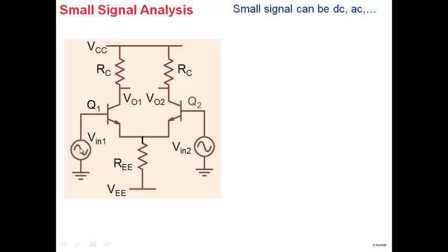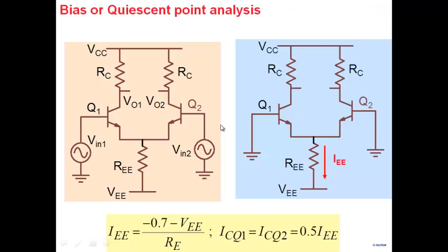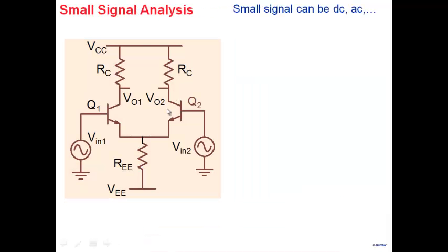All right. The difference is, if you're wondering, in this case also we have done a DC analysis. This is not DC. The proper name for this is bias point. So we have taken an amplifier which is biased at a certain point. So that's a bias point. It just happens that, yes, the biasing is done through DC voltages and currents, right? So it's a bias point analysis here. And the next one is a small signal analysis. The small signal could be a DC, AC, square wave, whatever it is, but it has to be small in nature, which we have seen earlier,